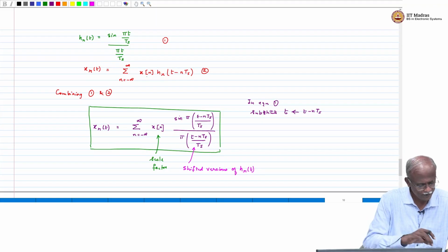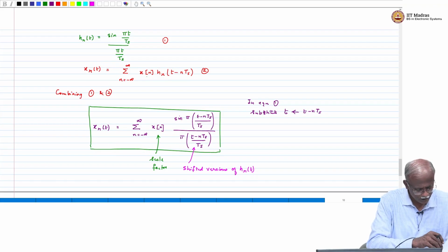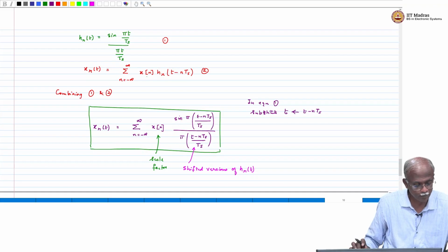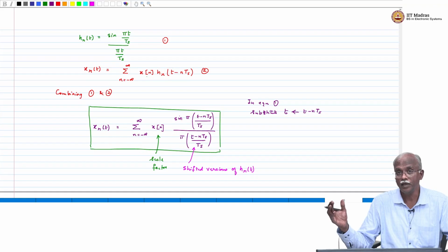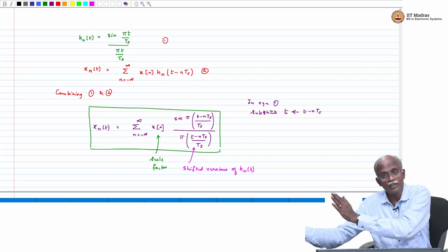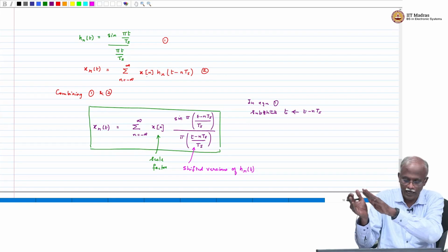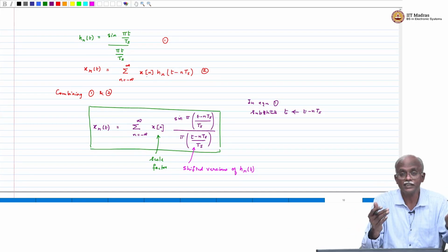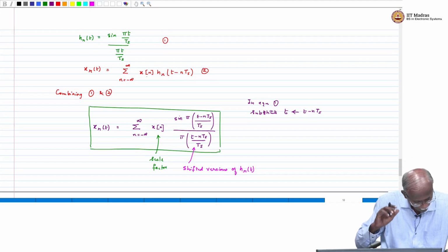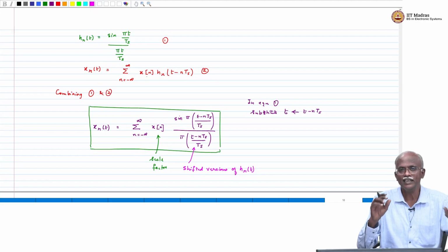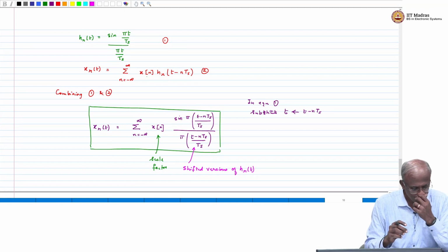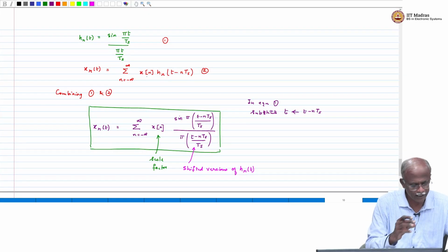Okay. So I am now very confident that you have the ability to understand how the reconstruction process is working, and how we can go from the continuous time to the discrete time through an intermediate step where there are Dirac delta functions. And then when you go from the discrete time back to the continuous time, again we generate the Dirac delta functions and then convolve with the reconstruction filter, and what the reconstruction filter is, we can understand by looking at the Fourier spectrum of the sampled signal. So please do look at this material more carefully, go through it, understand what the concepts are, and definitely you will find that this is a topic that will be of interest and something that you will be able to understand and apply very nicely.